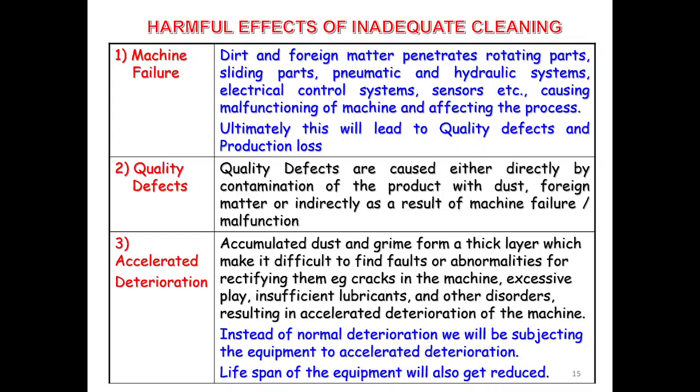Accumulated dust and grime form a layer which make it difficult to find faults or abnormalities for rectifying them at the earliest. Example, cracks in the machine, excessive play, insufficient lubricants, and other disorders, resulting in breakdown of the machine. Instead of normal deterioration, we will be subjecting the equipment to accelerated deterioration. Lifespan of the equipment will also get reduced. Hence, cleaning is given paramount importance and is the first fundamental step in TPM.